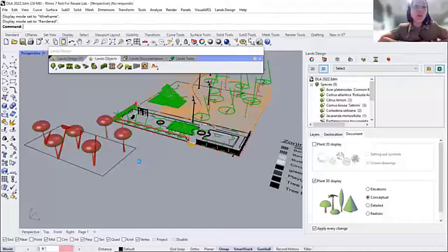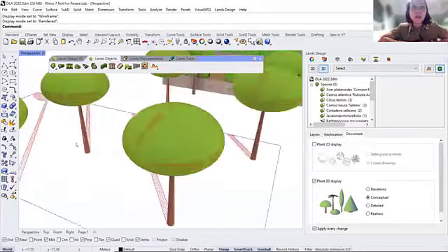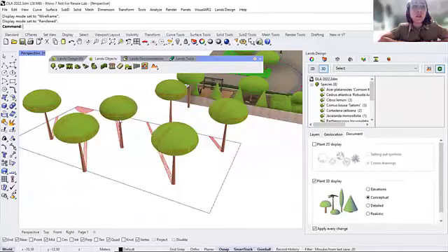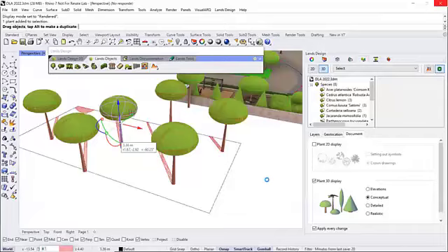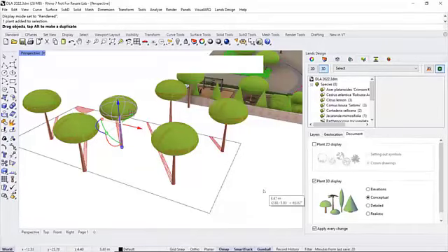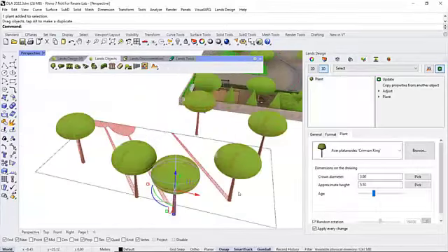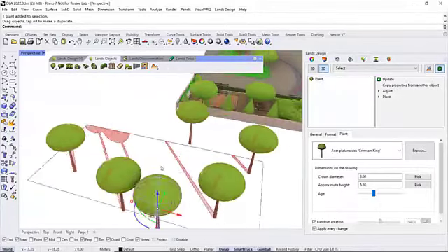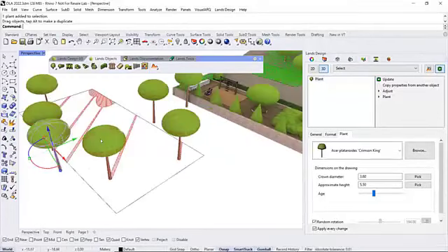The conceptual shape maintains the same diameter of the plant, so it's quite enough for calculating the shadow. For the conceptual mass, it'll be fine. They're all set for age of plants in the Estidama report anyway, so that's fine. Good. Here it is, all the shaded area, based on the conceptual shape.